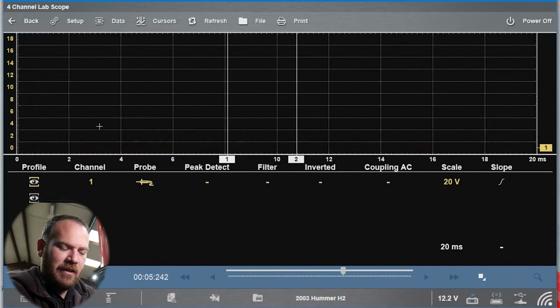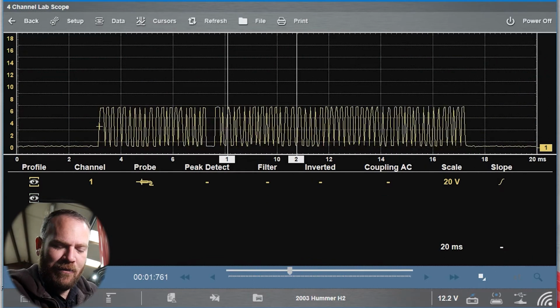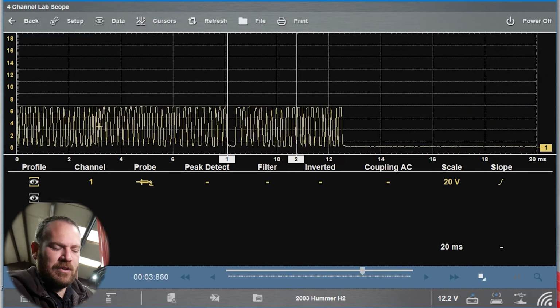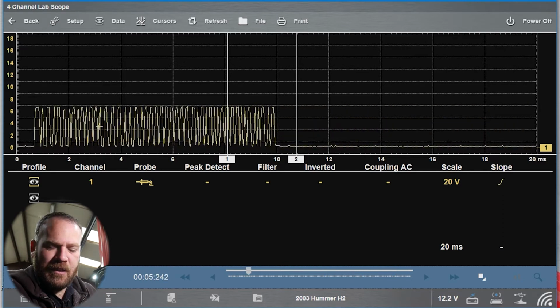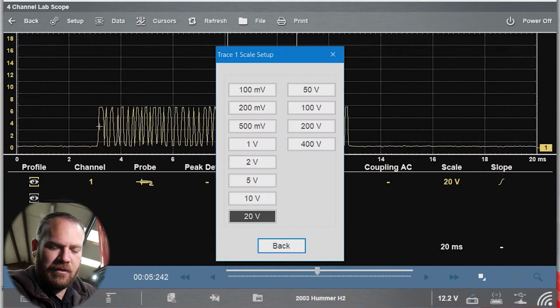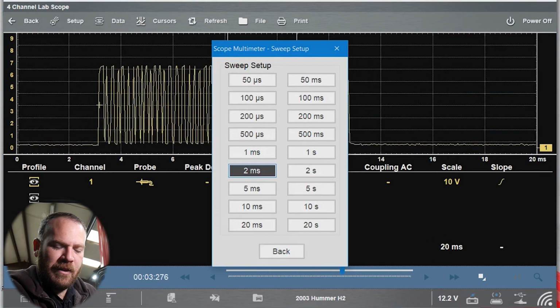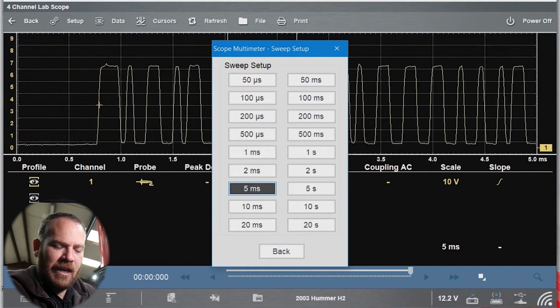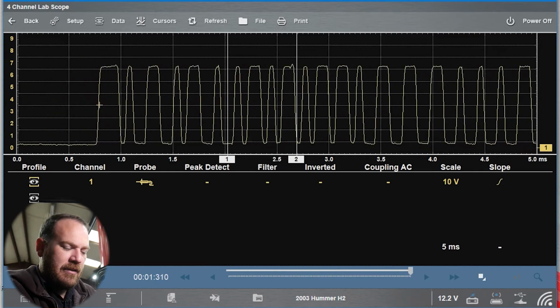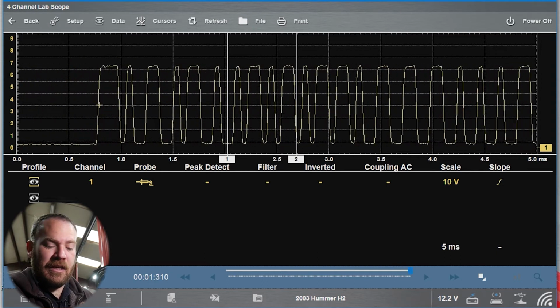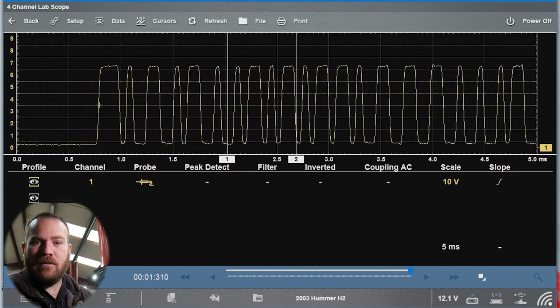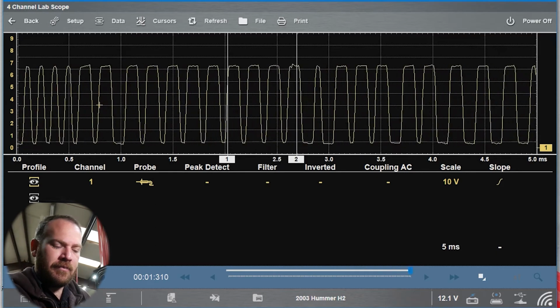We can shut off the alternator waveform there that was making some noise. This communication line looks just fine. If I really zoom in, we can see what the actual signal looks like. And keep in mind, I have my scanner plugged in, which may affect the signal slightly.